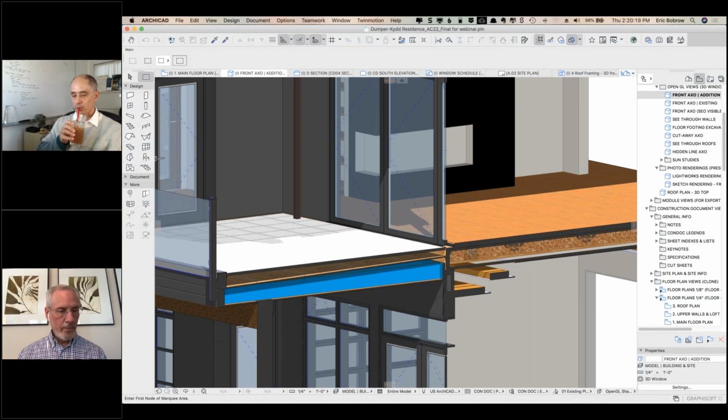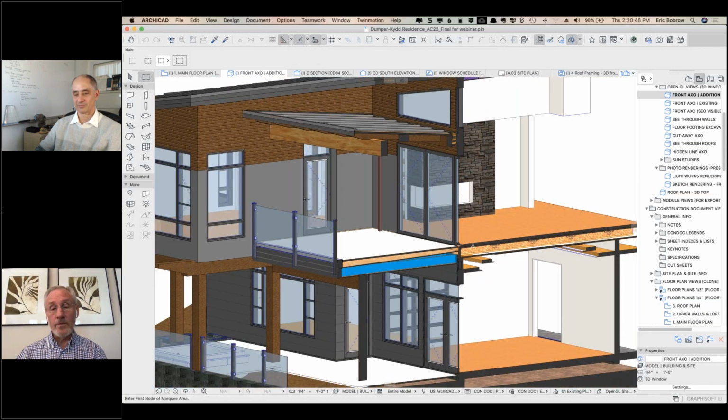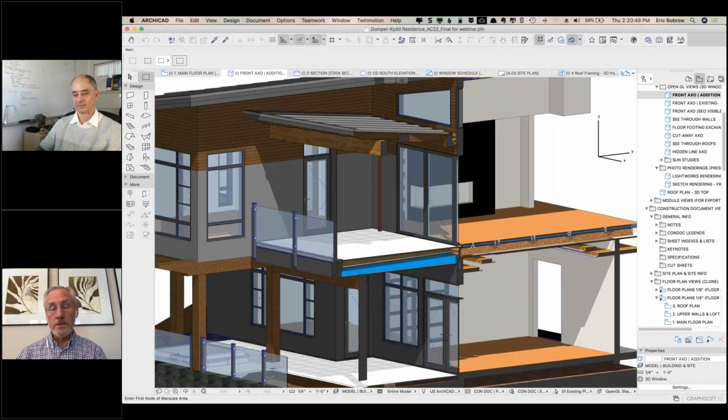And the pucks that support these things, other people have probably seen these things. You can do wood on them as well. There's a small gap, about 1/8 of an inch between each of the pavers, so the water just goes right down through. You never see it. It never pools at all, and it's a lovely finished deck, and the client doesn't know what's underneath, really. He doesn't care. But it's an expensive deck, but if it's in the budget, it's a nice thing to have.